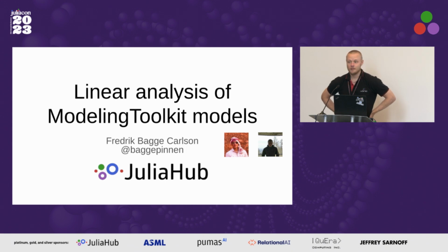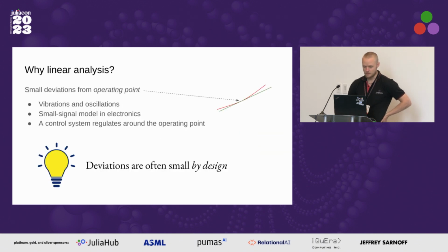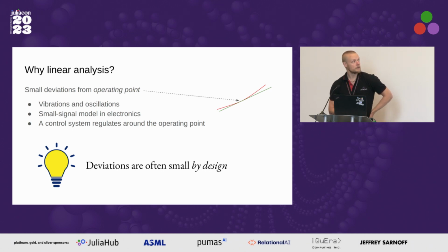Today I will talk to you about linear analysis and how we do that in ModelingToolkit. All right, so we'll start by talking about why we might want to do a linear analysis. We typically do a linear analysis when we have small deviations of our dynamical system from an operating point.